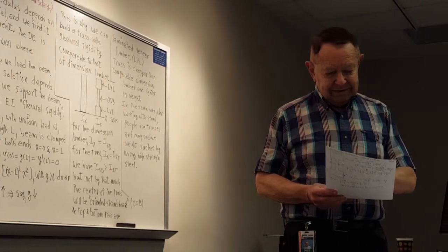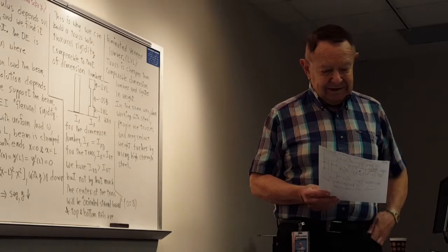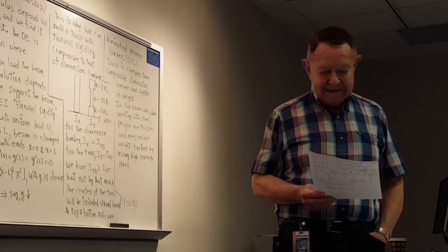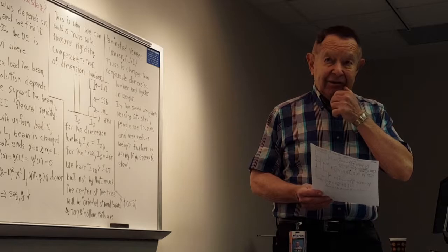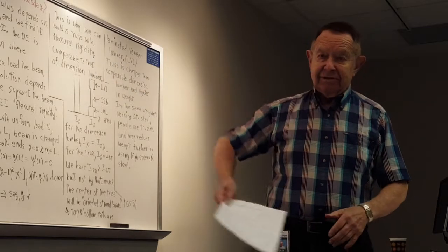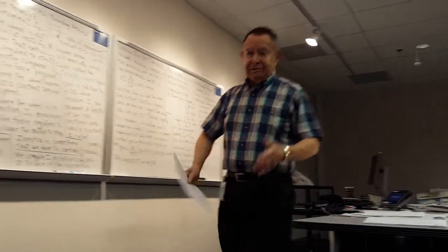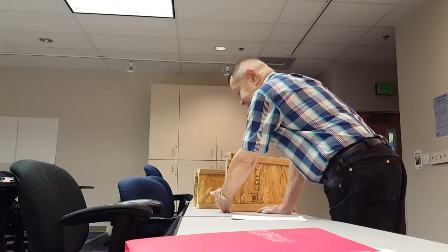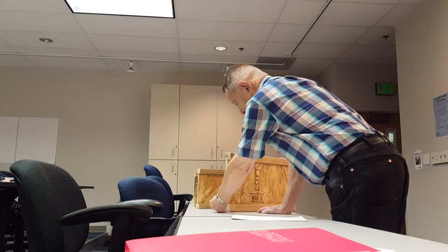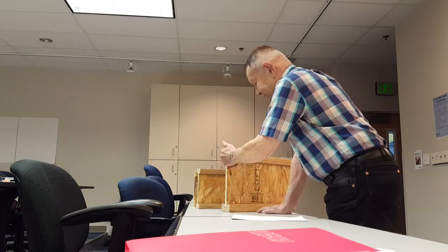So if you're looking at the cross-section for a joist to replace 2x10 dimension lumber, although your moment of inertia is really a double integral, if you have uniform material, which you would certainly assume any of these would be, then what you really care about in your moment of inertia is the squared distance from this axis down here going this way.